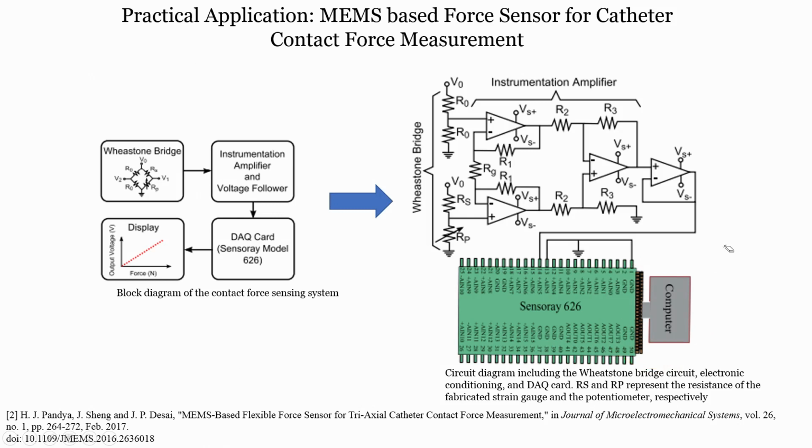So, here you can see the first thing that we are using is a Wheatstone bridge, right. We have seen the advantage of Wheatstone bridge over potential divider. If you do not know, you can just quickly see why we are opting for Wheatstone bridge instead of a potential divider or a resistive divider circuit. So, this is a resistive divider circuit, and if I have this resistor as sensor resistor, and this is a fixed resistor R equals RS when there is no force applied, right.